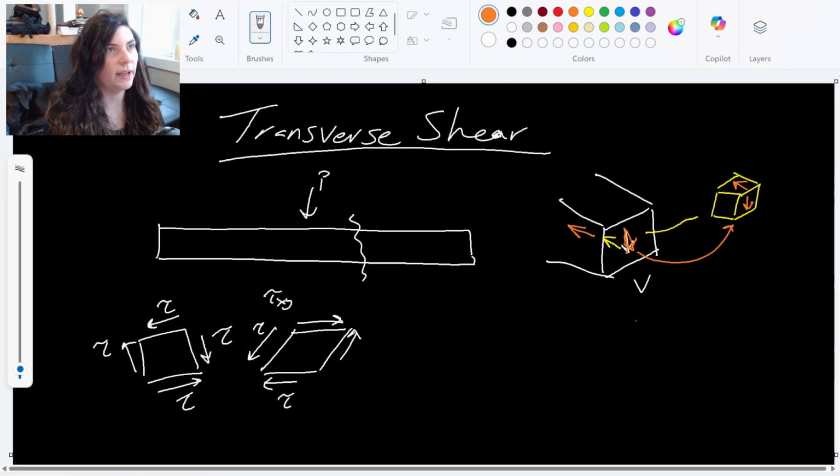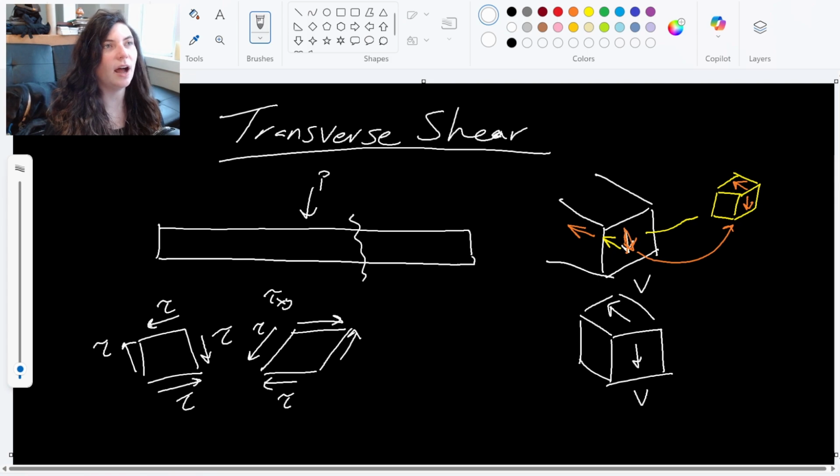So everywhere we have a shear stress on this face, there's our shear V, equal and opposite shear. I guess this is the same picture that I just drew. Equal and opposite shear where there's no shear on this front face. So this face experiences no shear whatsoever. It is through the beam, right?